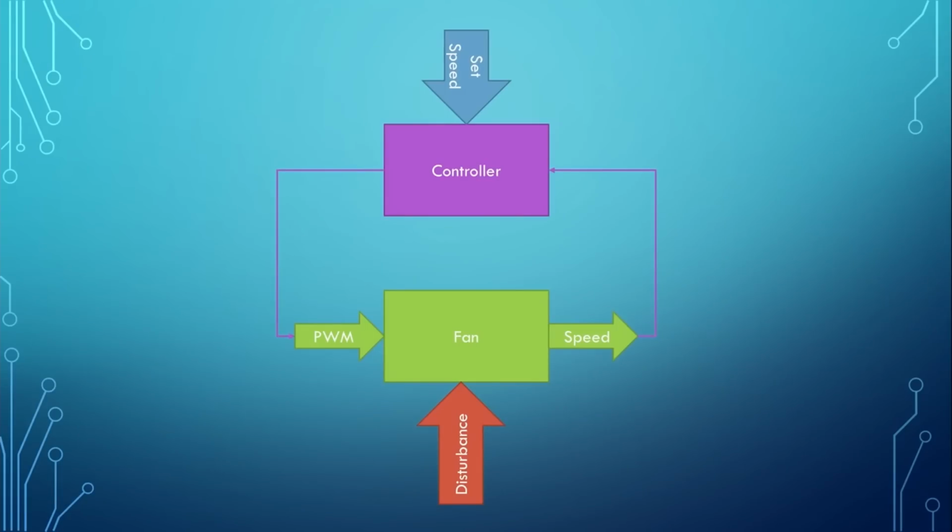What we need now is a so-called closed loop system consisting of the fan and the controller. The controller measures the speed of the fan and adjusts the PWM signal accordingly. I could do this manually, but I do not want to show you this example because it is quite clear that I do not have 4 hands to block the exhaust and adjust the PWM signal at the same time. In addition, I would be way too slow.